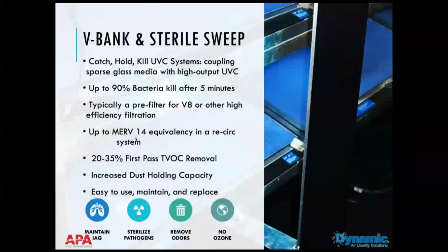A fun fact: this was used as part of the anthrax cleanup. Not to kill the anthrax, as they used chlorine dioxide in the buildings. They sealed the buildings up and pumped them full of chlorine dioxide for a month. But when they flushed the buildings out, they didn't want anything live to come in, and so they used this system for that. In a research system, this does very well in terms of particle reduction and removal. Not as good as the V8, but it's up there with high efficiency MERV filters.